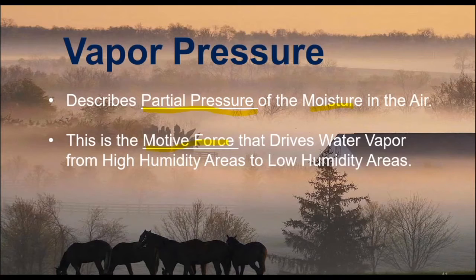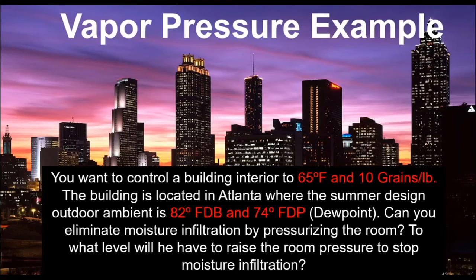From high to low. One way I remember it is to think about throwing a bucket of water up in the air. Which way does it go? High to low. Well, that's actually gravity, but anything pressure related is going to move from high to low. So vapor pressure, that partial pressure of moisture in air, is going to move from high to low.